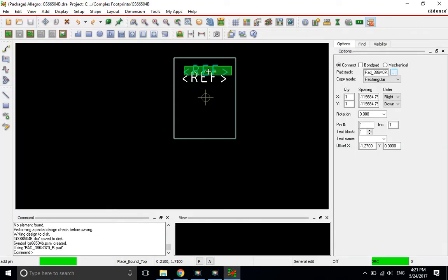Go to PCB Editor, and we're going to use the exact placement method. I'm not sure what to call it, but we use the coordinates on the keyboard to place the pad. The default location is 0, 0 in the center, the origin. So our x coordinate would be 0, and the y coordinate would be 2.91 millimeters. So let's type it in: x space y space 0 space 2.91. Enter. The pad stack has been placed.